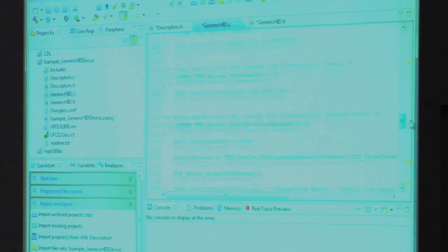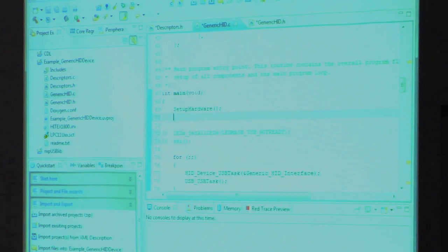Now, one thing I still need to do is, when the part is initialized at reset, all the port pins are inputs. So what I need to do is set port 0.7 as an output, right? Setting a 1 in that position sets that particular port pin as an output.